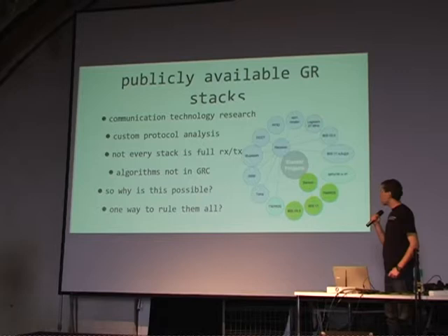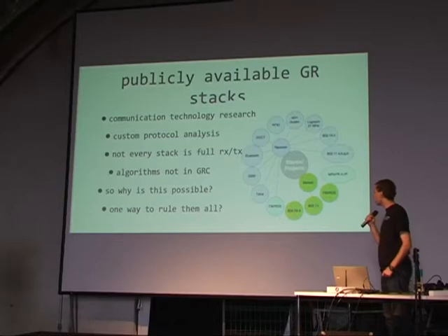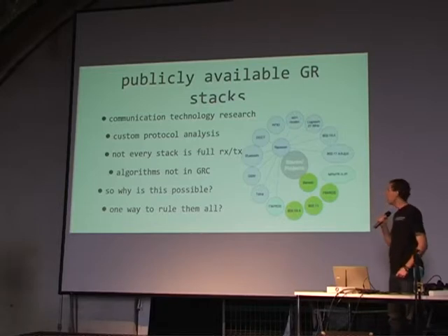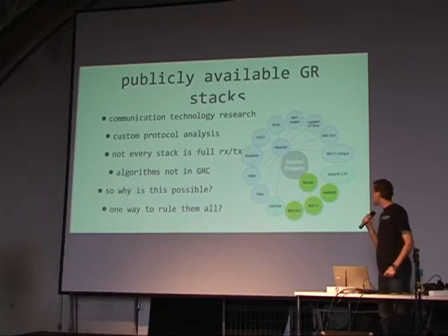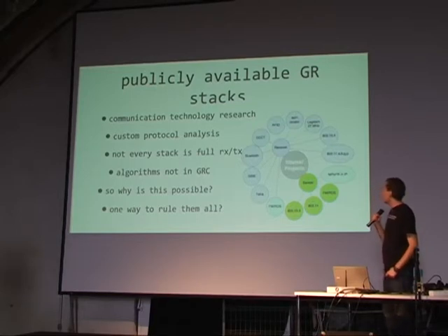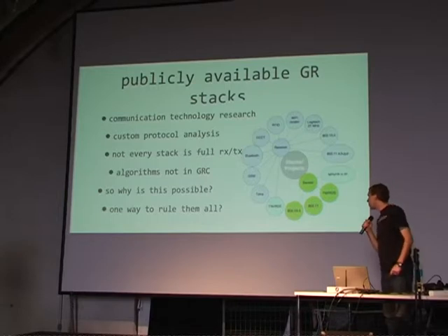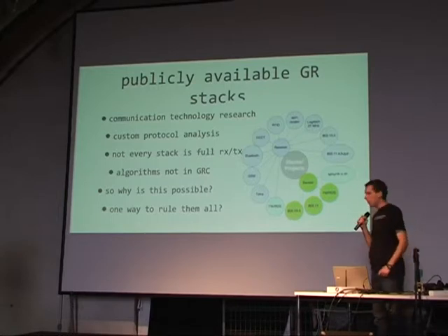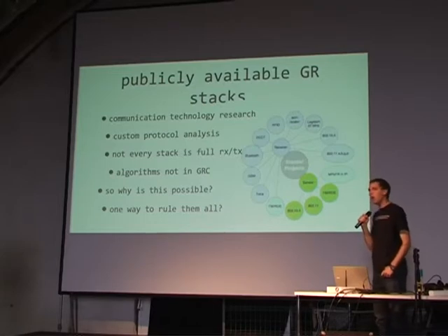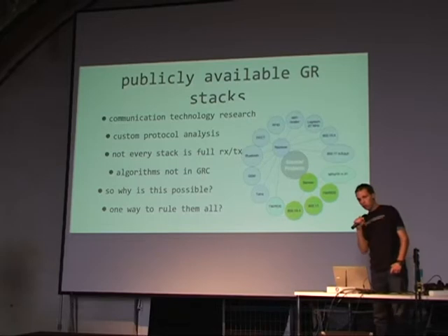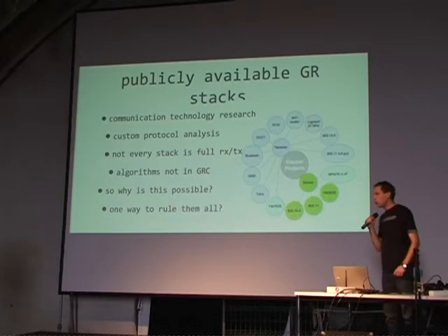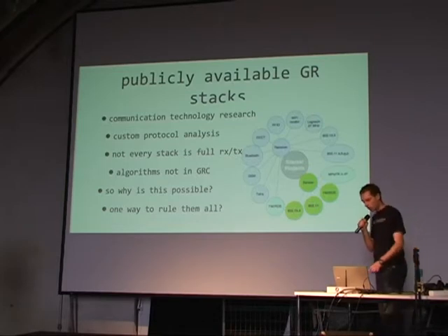But all these stacks also define a sniffer. So I have mentioned that we have senders and receivers. Not every stack that is mentioned here has a sending path implemented. But practically receiving DECT with the USRP is possible, or Bluetooth, or Wi-Fi, or GSM, Tetra, whatever. The algorithms aren't necessarily in the graphical components of the radio yet. So due to the design of using an ADC with an FPGA, we can actually expose our code near enough to the hardware so that we can realize the general approach to every one of these transmission schemes and standards.